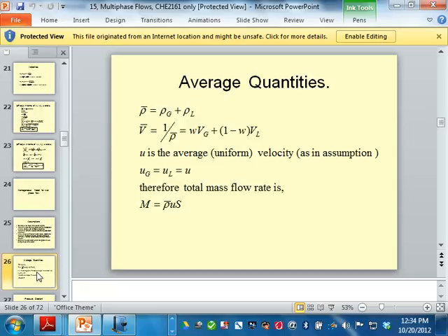I think there's something wrong with the top one. Doesn't look quite right. Okay, never mind. Ignore the top one. We use that one. Again, in reality, the gas and liquid can be moving at different velocities, but we assume there's one uniform velocity. This is part of the homogeneous flow model in pipe. That's why I separate the two. Earlier this morning, the gas and liquid in the bubble column were moving at different speeds, and we studied that. But in this case, we assume there's one speed.